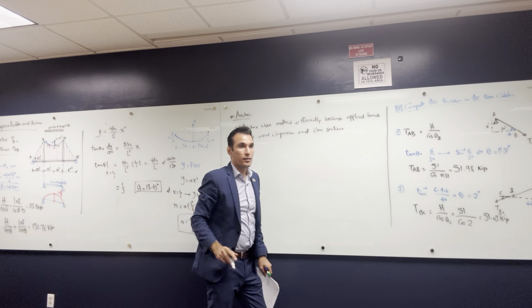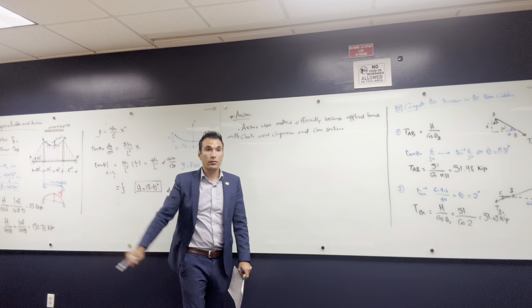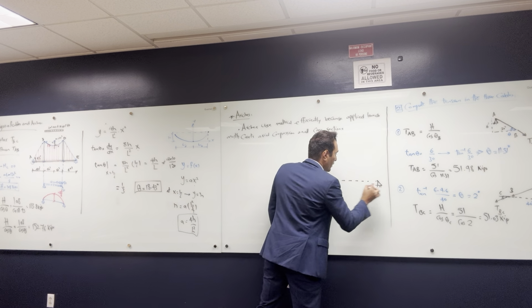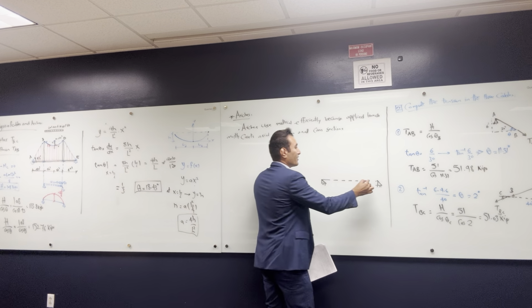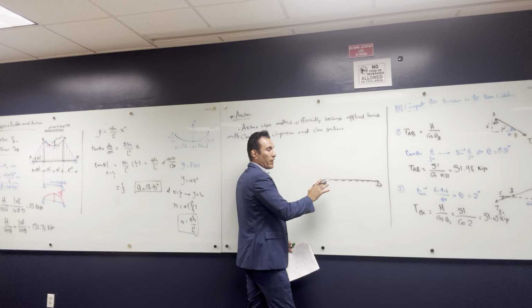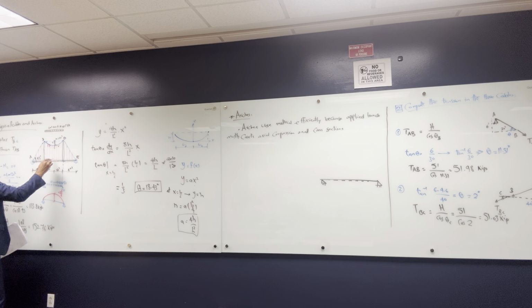All right, the thing is, let's say that we have this space and the span from here to here is like, I don't know, 20 foot, okay? So you have a span that's 20 foot. And you need to cover this space. There are different ways that we can cover this space, like to make this slab. It's either you make a simple beam from here to here and make something like this, right? Or what I'm gonna do is something like what we did here. A tower, and then we hold this with cables. You'll tell me, but right now I have a slab and I have cables. The thing is, this slab is gonna be very thick.